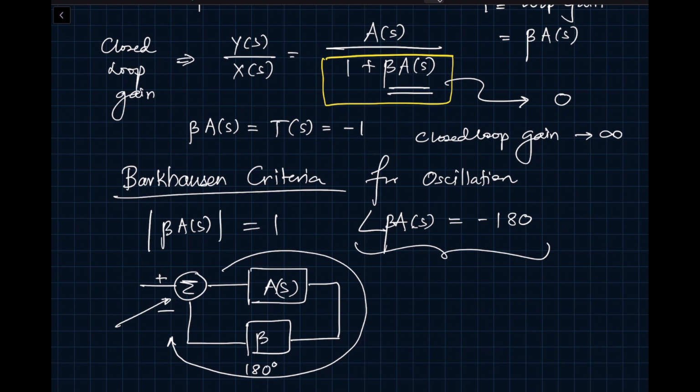The reason we call it positive feedback is that we have 180 degrees and yet another 180 degrees because of the inversion, as a result of which we have oscillations. So in general, when we are designing the amplifier, we would like them to be stable. We really do not want them to oscillate unless we are trying to design an oscillator where we intentionally want this particular phenomenon to happen so that our circuits can oscillate. That part we are not going to cover in this class. So we will focus on making sure that we design our amplifiers which are stable and they do not oscillate.